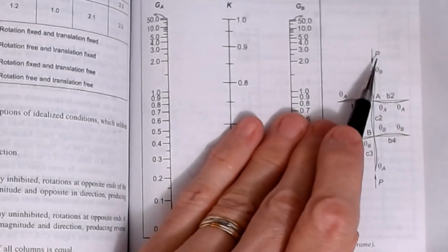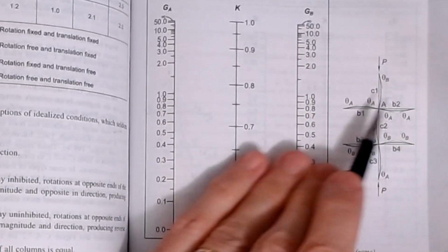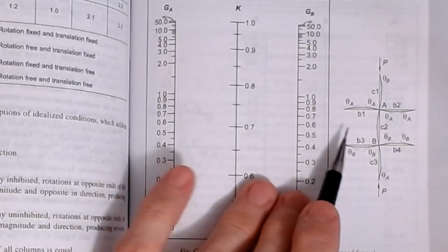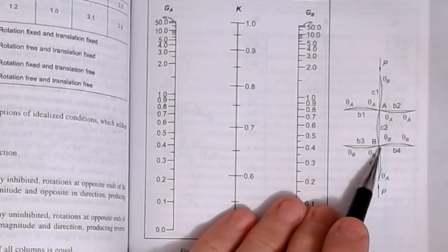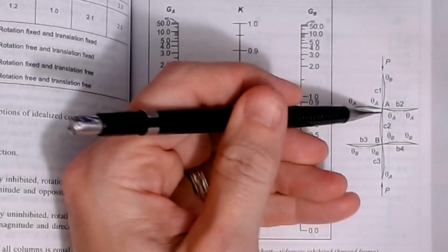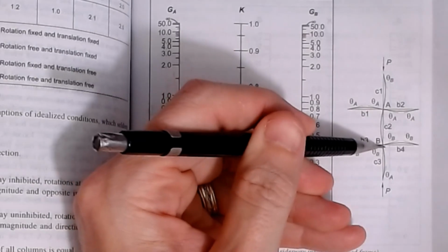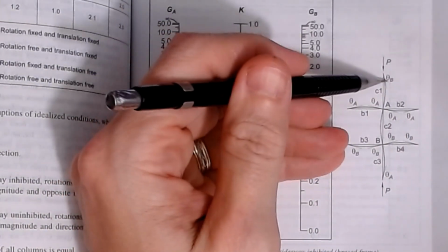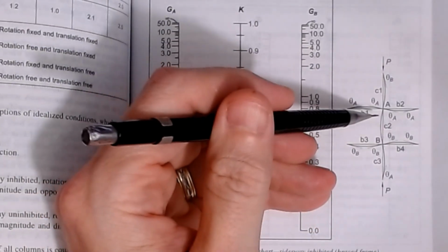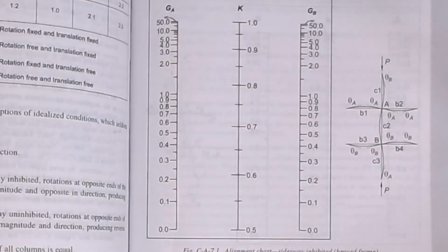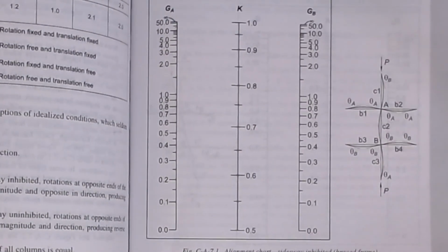And so we're going to look at the columns and the beams that come into A, and then use those to compute this GA parameter. And likewise, we're going to look at everything coming into B, in terms of the beams being the horizontal guys, and the columns being the verticals, and everything that they share at that node. Okay, now if you're at the top of the building, it's possible you don't have a column above. If you're framed differently, it's possible that you don't have a beam on one side, if you have a two-story atrium or something like that. So there's lots of combinations that come out of this.